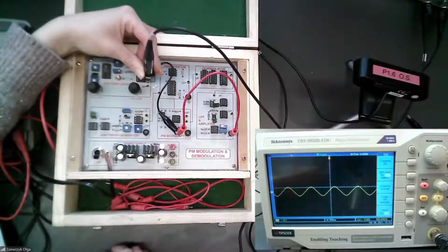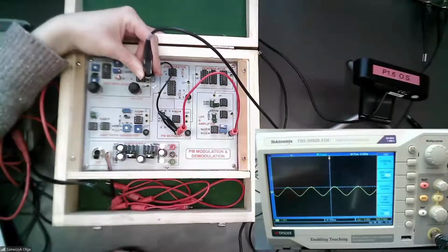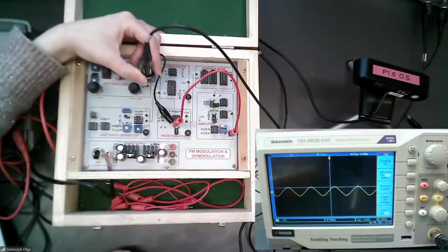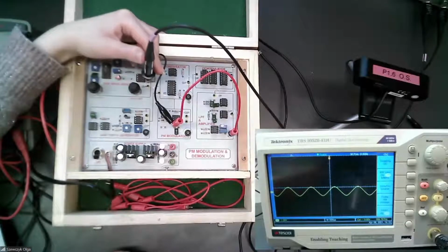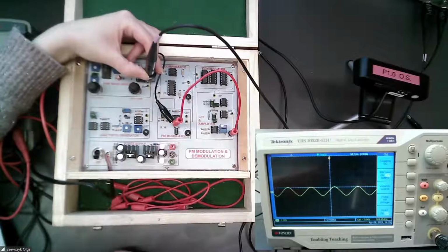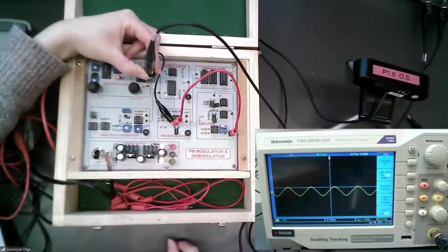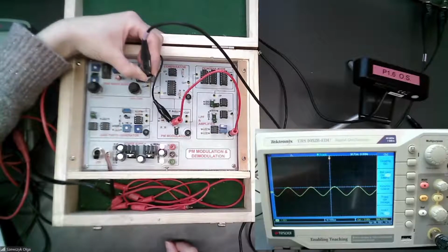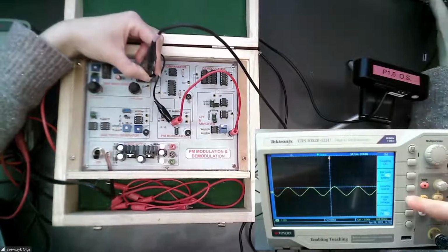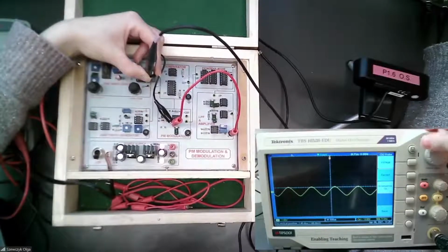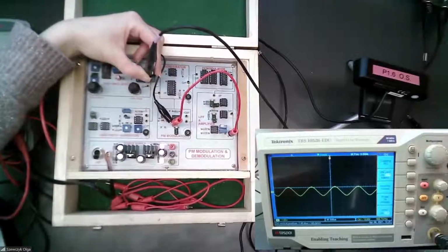One student asked about the oscilloscope multiplication, because sometimes we change the multiplication of the oscilloscope probe to ×10. So actually, this digital oscilloscope contains such a function. As you see now, it's set to ×10, so it should be set to ×1.